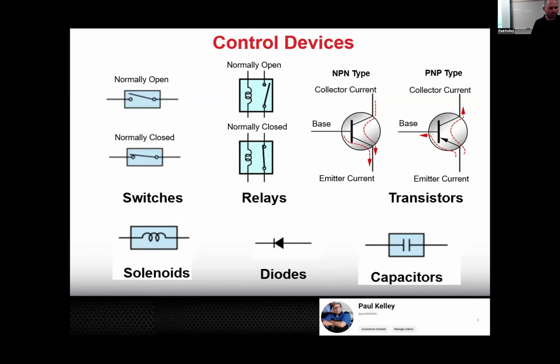So after it goes through, does it go back to open again because it's gone, the voltage is left? So that's, if you look at the left side, anytime the left side has 12 volts and ground, this switch is closed. And when this switch is closed, we're usually sending bigger power, 15 amps, down to the fuel pump. It'll continue to send 15 amps down to the fuel pump as long as we have 12 volts and ground here, right?